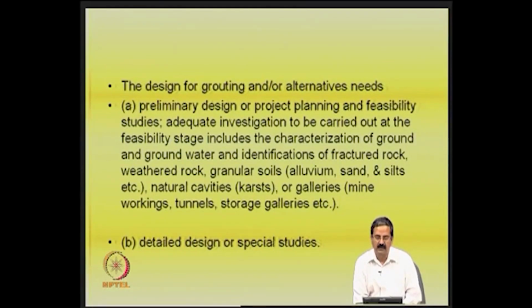So, how do you fill up all those fractures, cracks, joints and all that? You should also be able to know about the degree of weathering of the rock. Granular soils also should be known, for example, what type of soil you have, alluvium or sand or silts, etc. And you should also have information about natural cavities and galleries, like mine workings, tunnels, storage galleries. There could be many openings underground. One should be very careful.